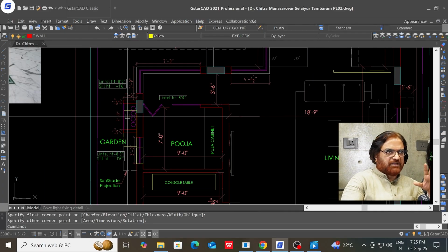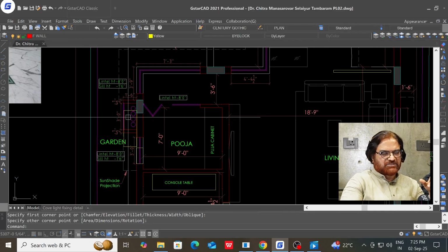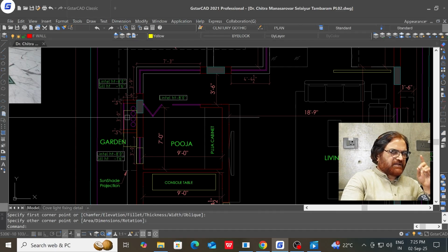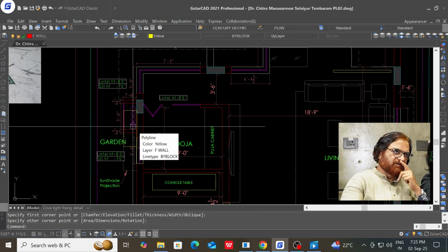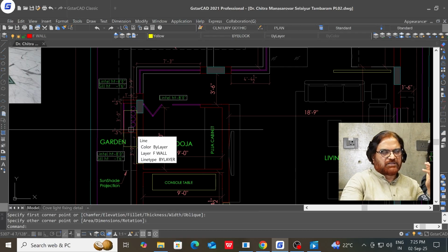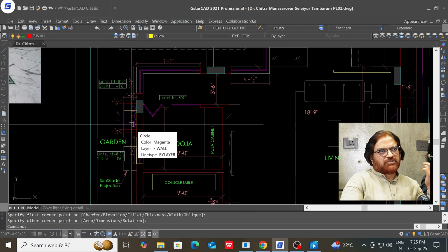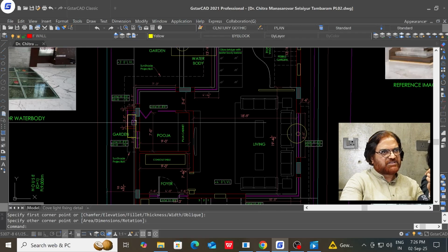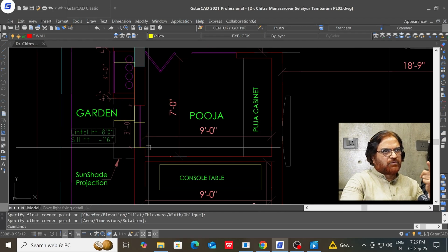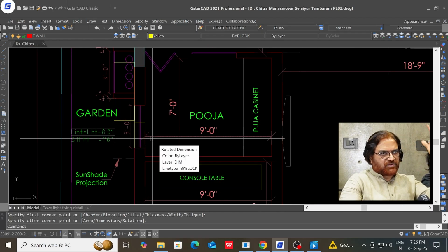We are not only bringing the plumbing things into this, we are also bringing the air conditioning, we are bringing the CCTV camera lines, we are bringing network lines. Everything comes through the duct nowadays. What duct, the sanitary duct we used to call, used to be only 1.5 to 2 feet. Nowadays, even 3 feet is not enough. So I would like to see this at least 3 feet. So we are going to reduce this window and make it taller.